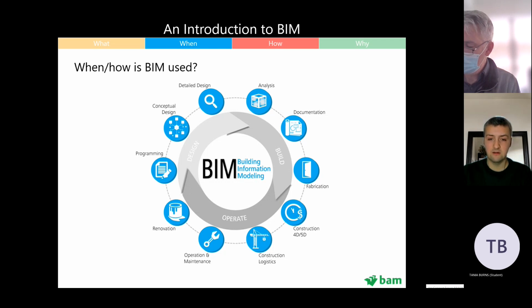Then you get to the floor slab, and you input the date from the program to the floor slab, and you do that for the whole building. At the end of it, you can basically press play, and it plays a video of your building going up exactly as your construction program says. I think the second lecture will show you exactly what that looks like. But it's a really powerful tool for checking that your construction program makes sense.